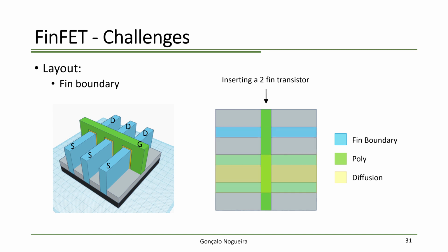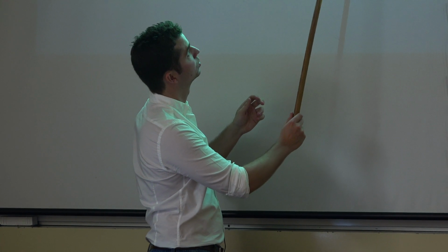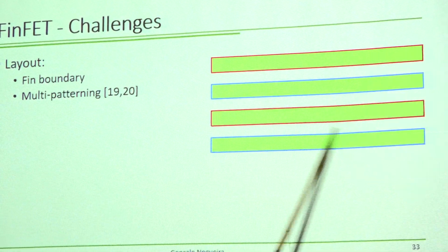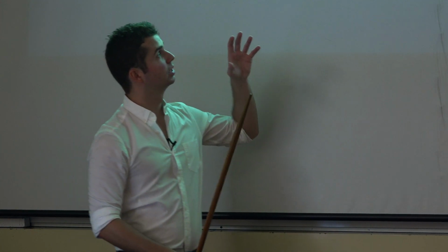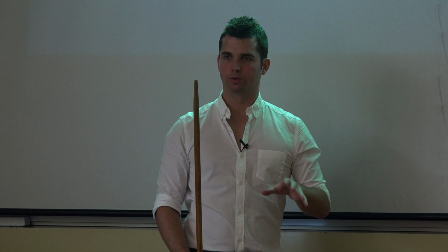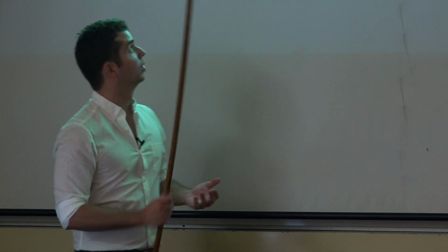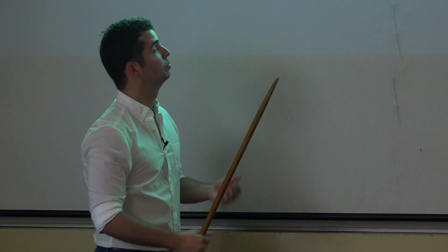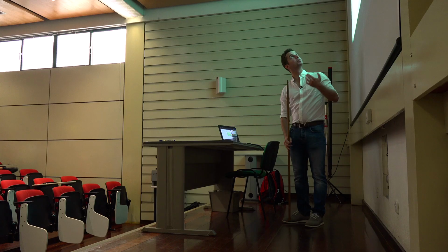Also, besides this, you've got multi-patterning. This is to be able to have metal lines which are closer to each other. If the foundry was trying to do these metal lines with only one layer, what would happen would be quantum effects, where this could merge, or there could be a hole, an open circuit somewhere.